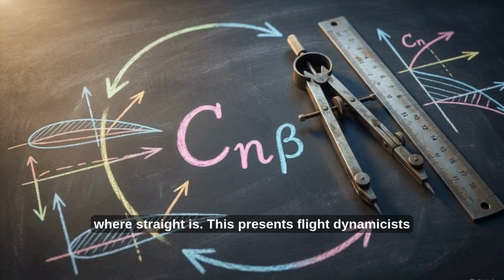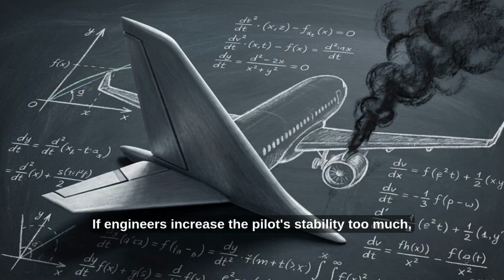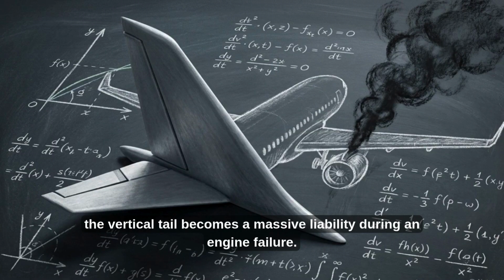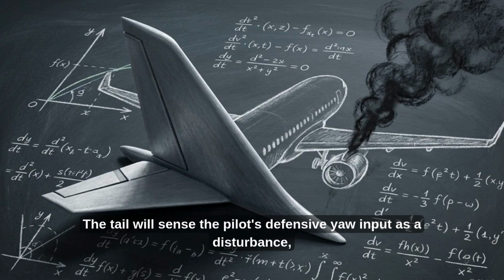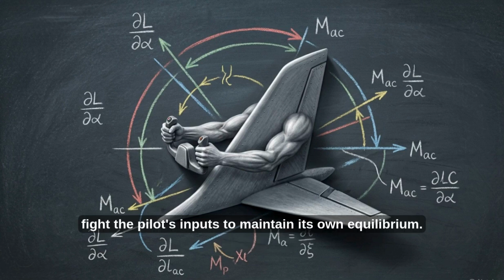This presents flight dynamicists with the ultimate optimization trap regarding the Cn beta derivative. If engineers increase passive stability too much, the vertical tail becomes a massive liability during an engine failure. The tail will sense the pilot's defensive yaw input as a disturbance, and it will aggressively fight the pilot's inputs to maintain its own equilibrium.